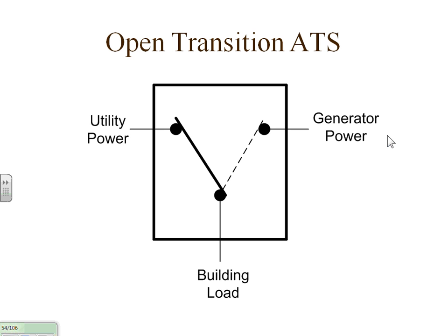It isn't legally required because we've got to be online in 10 seconds for NFPA for legally required systems. So this time delay, that's why I say it's kind of optional. And the only purpose for it is to allow the engine to run a little bit of time before you hit it with a load, to warm up, if you will. So, but we've already got the engine warm for NFPA situations with the jacket heater and stuff, so you shouldn't need that. Anyway, we're running on generator power now.